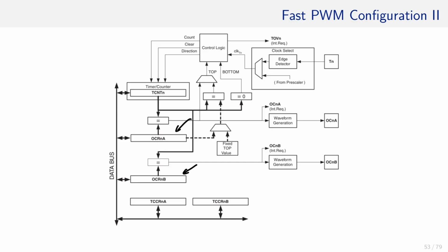If the standard period is fine, that is, TCNT counts to max, both OCRnA and OCRnB can be used to configure the duty cycle independently with the same period.